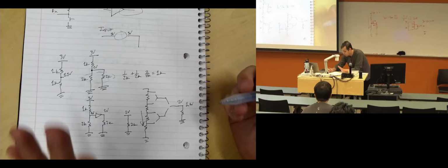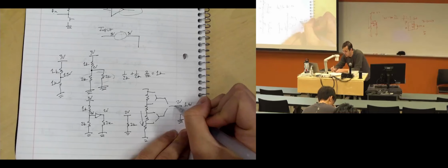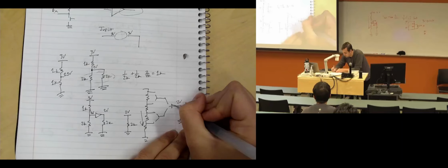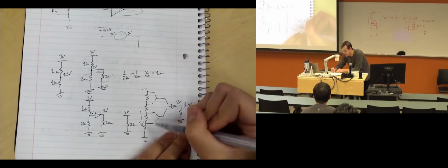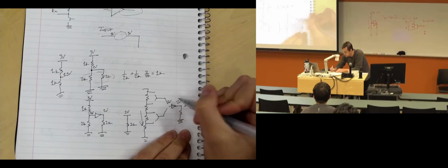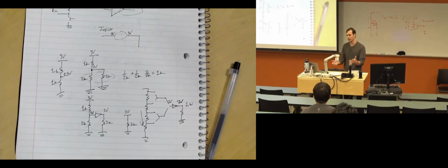So what's super common is right before it goes off to the pin, where you're allowed to use it, they'll put an output buffer on it, so that whatever voltage you actually selected using your digital value here, 2 volts, actually propagates to 2 volts on the outside, right? So that's a typical application of it that you're going to learn about later.